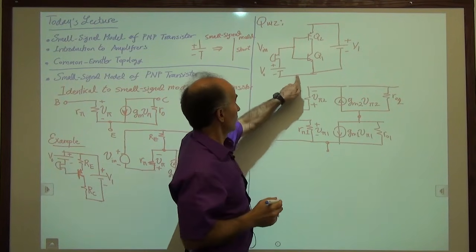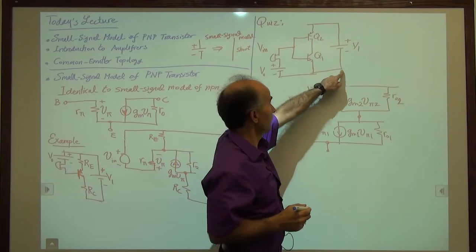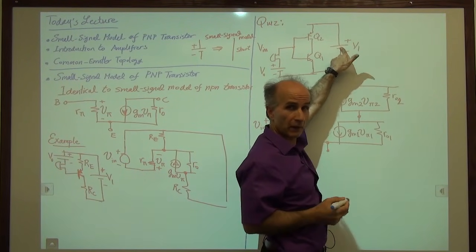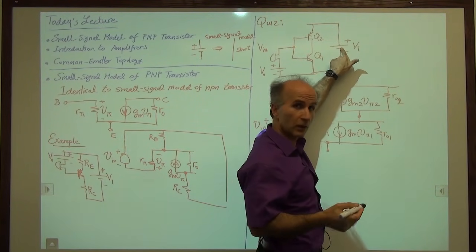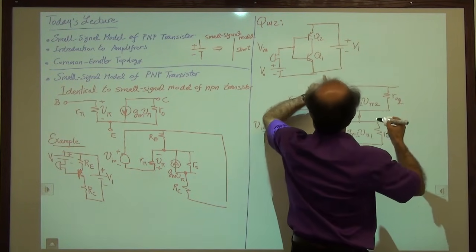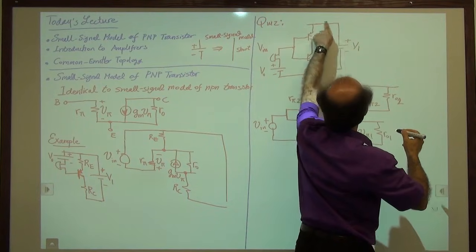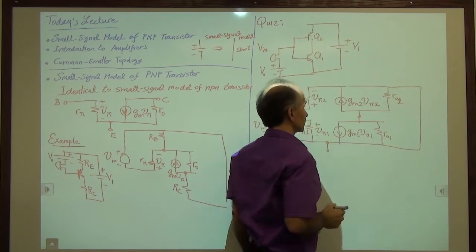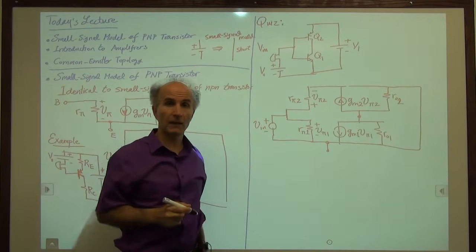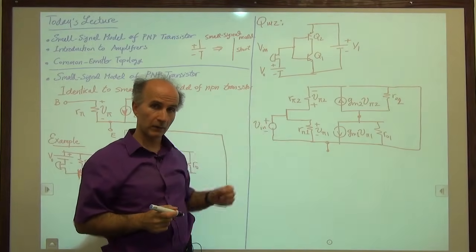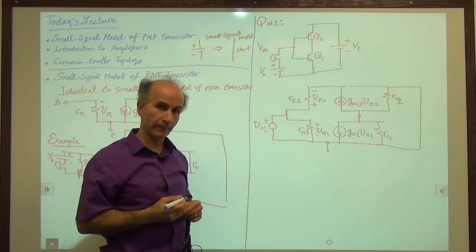And it actually goes to this wire, to the emitter, and continues. So it continues, and then it goes through another short circuit. We have another battery whose voltage doesn't change. Voltage change is 0. So that battery goes from this bottom terminal all the way to that top terminal. So it goes like this. And this is the complete small signal model of this particular topology.